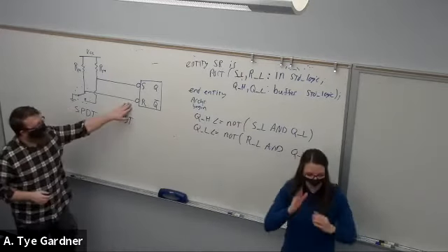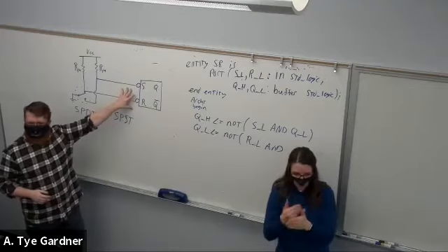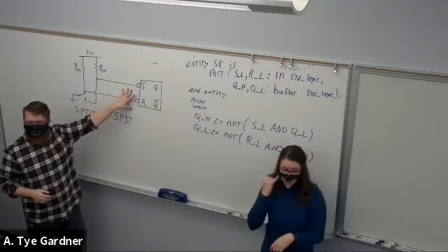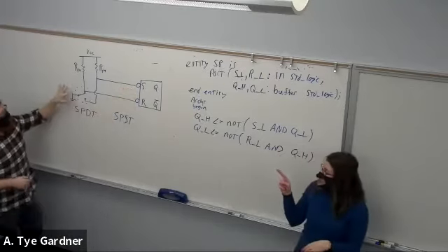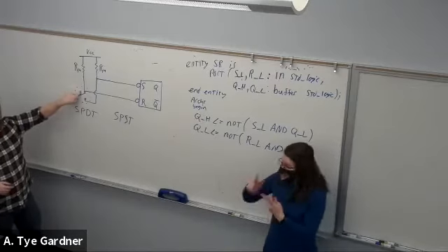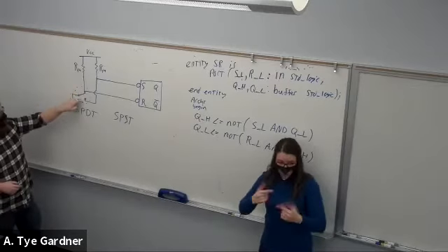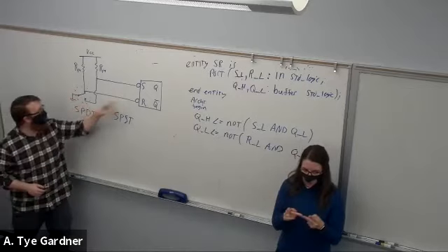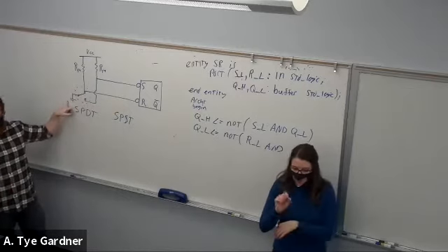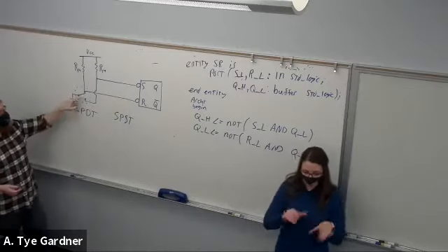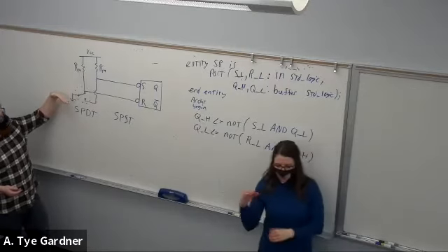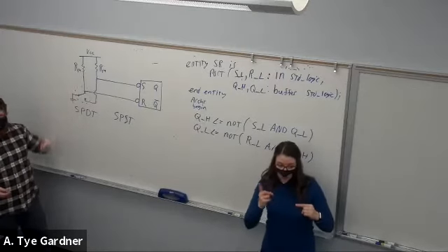But if you throw the switch on the set or reset latch, the SR latch, to the output of this, and I'm in the reset position right now, right? So I've connected reset to 0, it's active low. That means Q is going to be 0. Then I throw that switch to the other side to set.